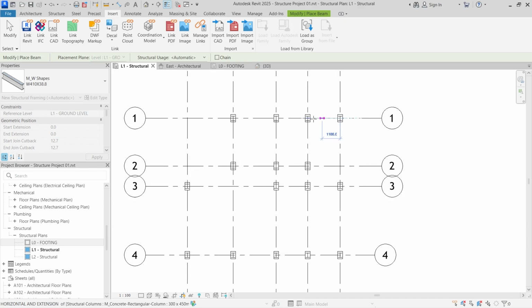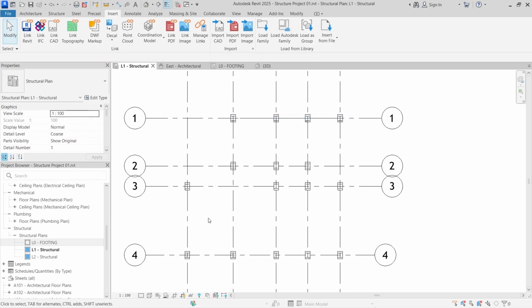Go ahead and click that point, and then you can run your beam just like this. You notice that we have an arrow popping up, but we cannot actually see the structural frame of the beam itself. That is because we're currently using a very low level of detail.